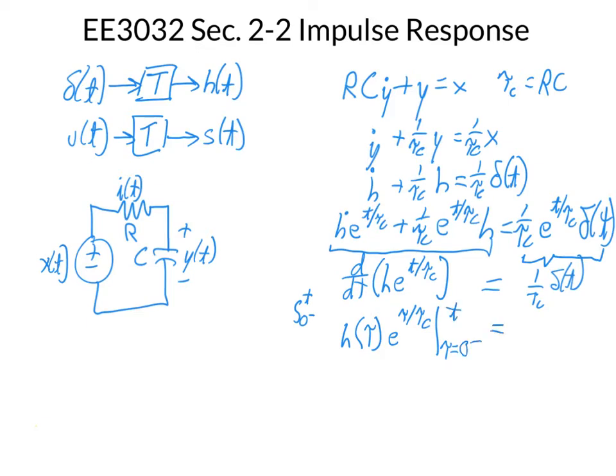And on the right-hand side, we also do the same integration from the left side of 0 up to whatever t is, and we realize we're just integrating over a delta function. So here we still have the constant out front, 1 over tau c. When you integrate over a delta function, you get the unit step, as we know from last week.